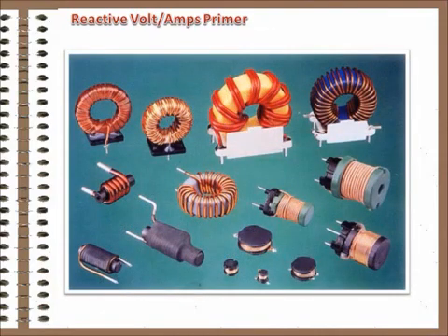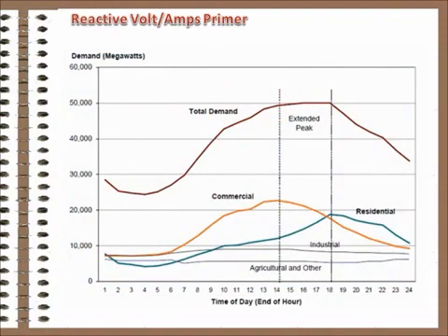The more coils of wire there are in the system, the more demand there is for this magnetizing energy. So, during the day, when motors are running, air conditioners are fired up, and transformers are heavily loaded, VAR flow is high. Power system operators say the load is inductive because the moving magnetic fields are said to induce the opposing current flow in the lines.